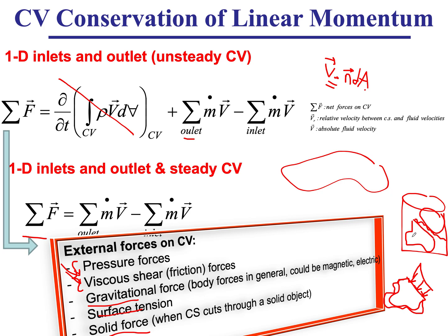So that was for a static fluid, because the definition of a static fluid is that it does not sustain any shear forces. But now, let's say in this cup you have a spoon, and you're mixing the fluid inside, you're stirring it, so you're creating a motion. And on this control volume, let's draw it again, you might have shear stresses, which will act parallel to the area that you have exposed. And similarly, you will have shear stresses on other parts that act parallel to the area that is under effect. And what is this shear stress that we have drawn here, this tau?